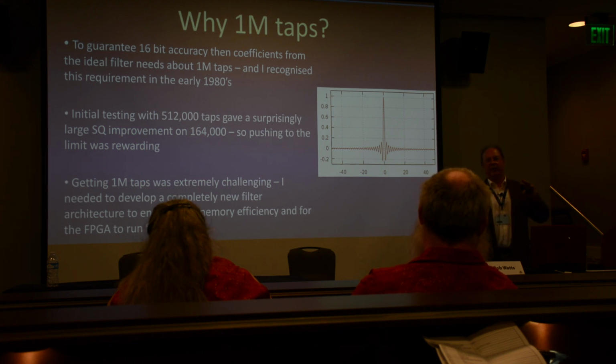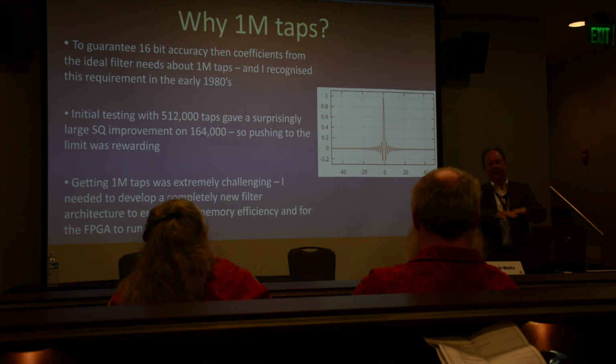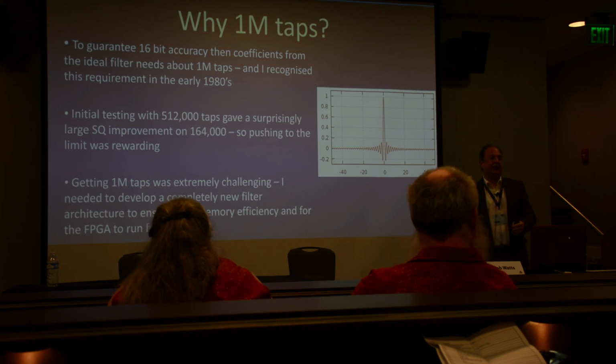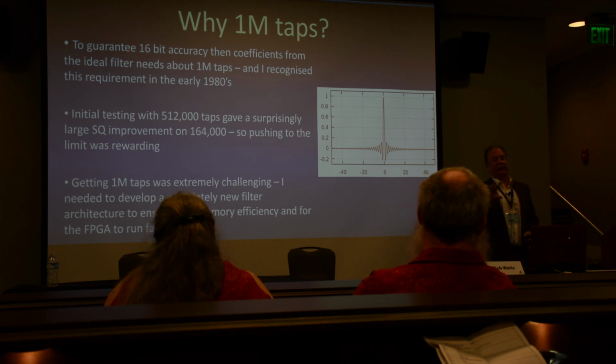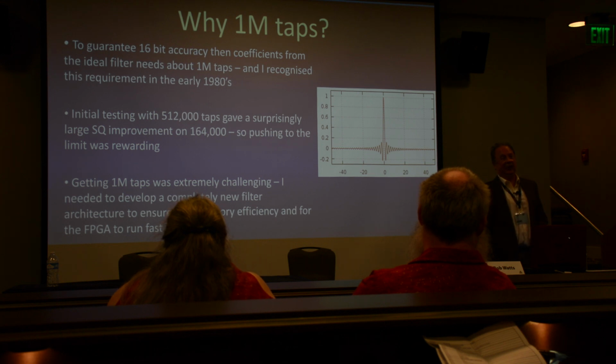Timing closure is when you design an FPGA, the FPGA tools place and route the design, and then do a check for you to make sure everything is going to be okay in terms of timing. Because if you've got a 9.6 nanosecond clock and it takes 13 nanoseconds to compute the result, you're going to get the wrong result. So timing closure is essential with FPGA work. In all digital systems you have to make sure your timing closure is correct.